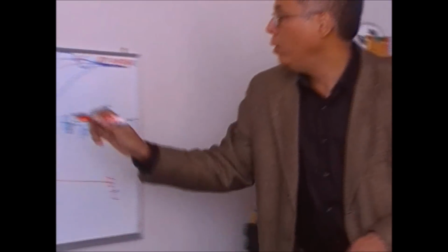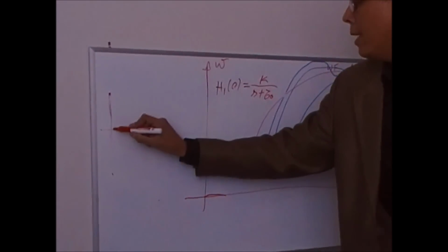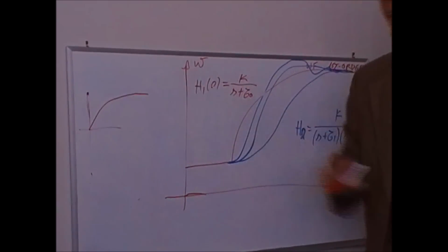In the experiment, you're going to take a motor and write code into the Arduino controller that will drive a DC-DC converter to create a voltage change at the terminals of the motor. That voltage change is going to cause the motor to accelerate, and it will create a response like this and stabilize.